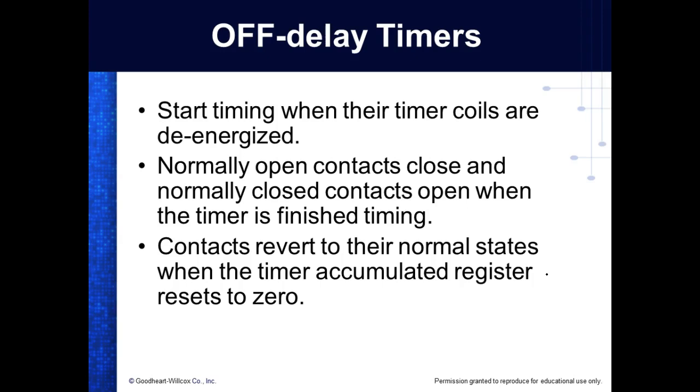Open, right? If it's a normally closed contact, if that coil is energized, it's going to be open. If that coil is de-energized, it's going to be closed, right? So the only time you're really concerned with examine if open, examine if closed, is if you're dealing with that stop button. Or it depends on if you're dealing with sensors, it depends on what that sensor gives you back when it's true. Does that make sense?